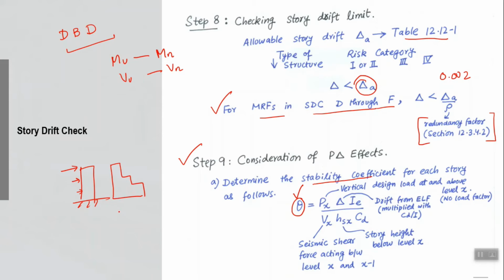It's just like the SFD or story shear force diagram of just one cantilever column, right? So first force, then it will be constant, then second force, third force, right? Similarly, story moment also you can plot like this. Obviously it will be highest at base and lowest at top.